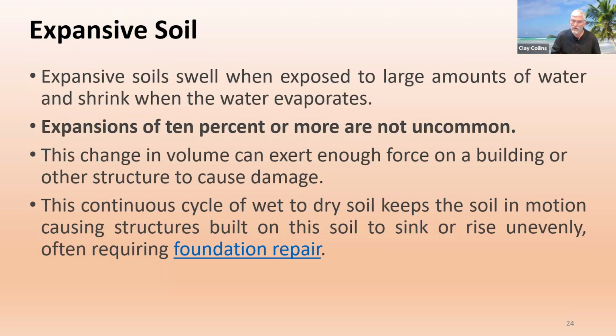But down here with the expansive soils, we know the impact of the water on those soils. If it's allowed to sit, the soil swells, it can impact the foundation, then it dries, it shrinks, which can impact the foundation. You have that constant movement, and that movement through a change in volume can be quite damaging.